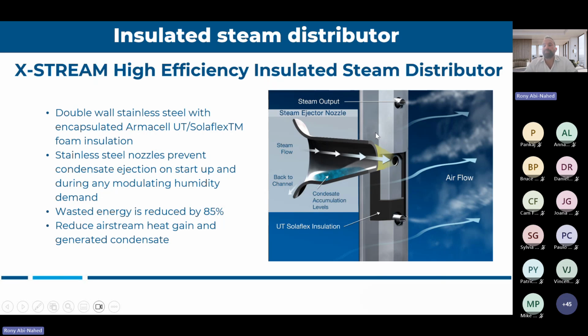Why? Because if you are not protecting your insulation with stainless steel, with time, if you have water dripping from the nozzles onto the insulation and into your airflow, the insulation itself will dry off, and by water dropping on it, it will perforate your insulation. After a couple of years, the insulation will start deteriorating and flying into your airstream. So ideally, you want a brand that, when they insulate, has stainless steel somewhere to protect the insulation.